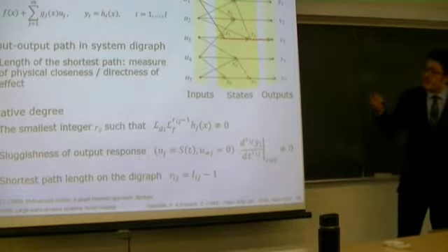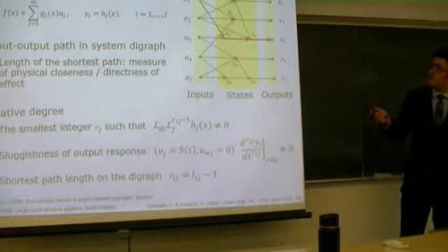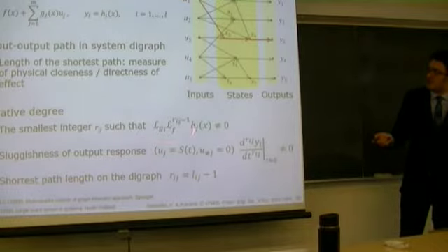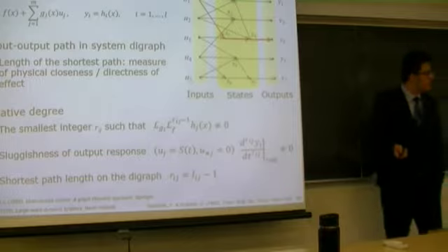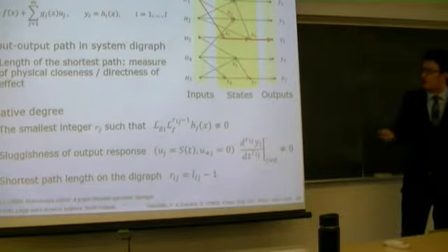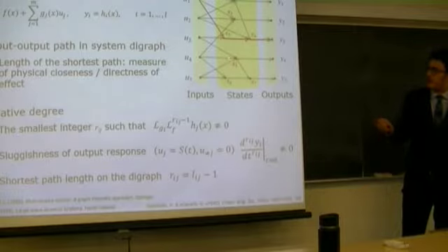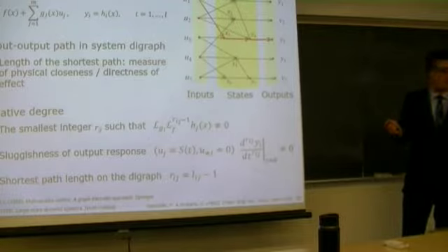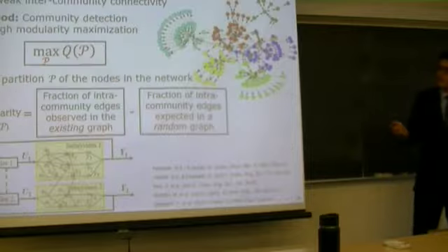Then there is a duality between the minimum path from one input variable to the output and the relative degree concept that we defined in nonlinear control. So by representing the whole nonlinear control system as an equation graph, we can use network theory to identify the optimal decompositions.